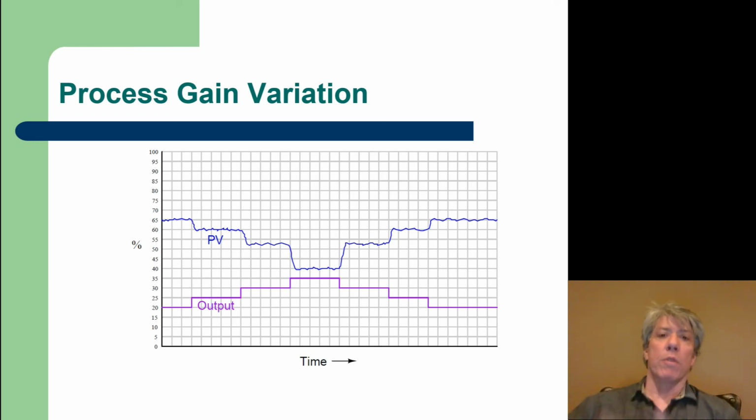I might be dumping more fuel in, but the wind resistance is nonlinear, and so the car simply does not respond the same way with as much change in speed due to the change in the control variable. Now that's kind of the opposite of what I've shown here, where the process is actually more sensitive to changes in the higher output ranges.